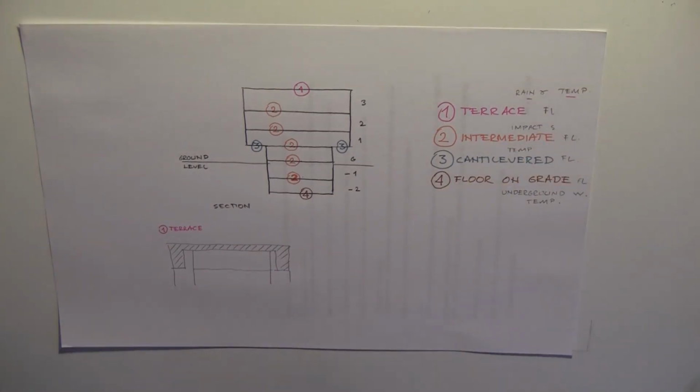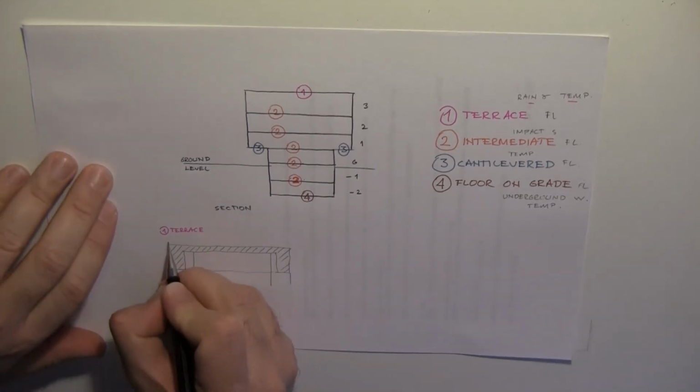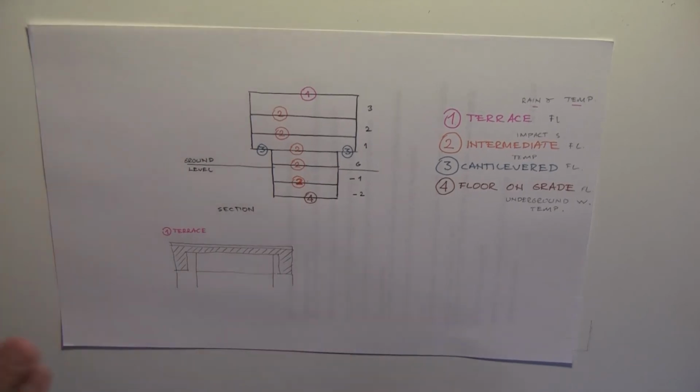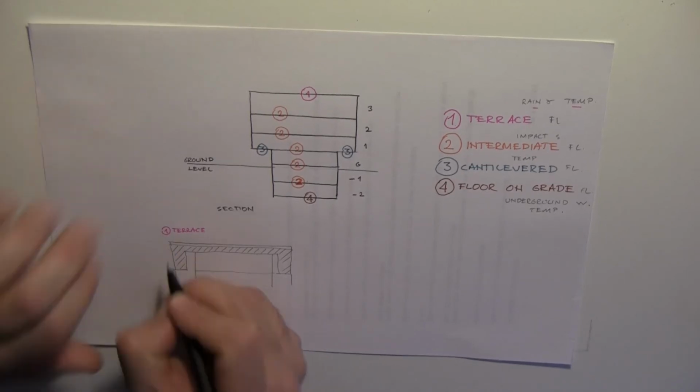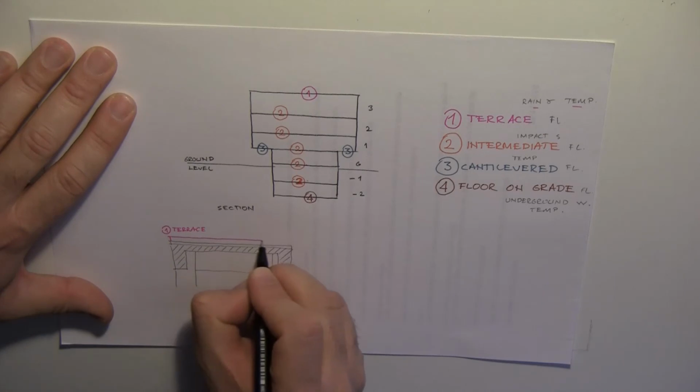Okay, you have got two options. Okay, the first thing is we usually place a layer of screed here. This is a layer of screed just to straighten and flatten the surface. Okay, and then we cover it with, okay, let's take pink, with an insulation.